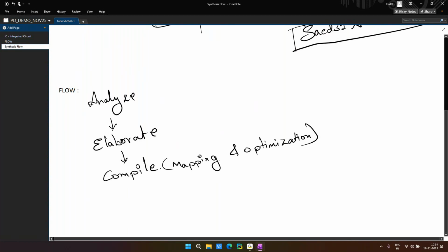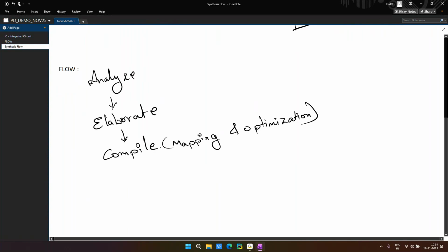The RTL designers have developed it, no? You will use that code. So have we implemented any DFT patterns over here? No. So now comes the next stage called scan configuration. You will load the scan configuration. That means DFT people will provide certain scripts, and we will load all of that.